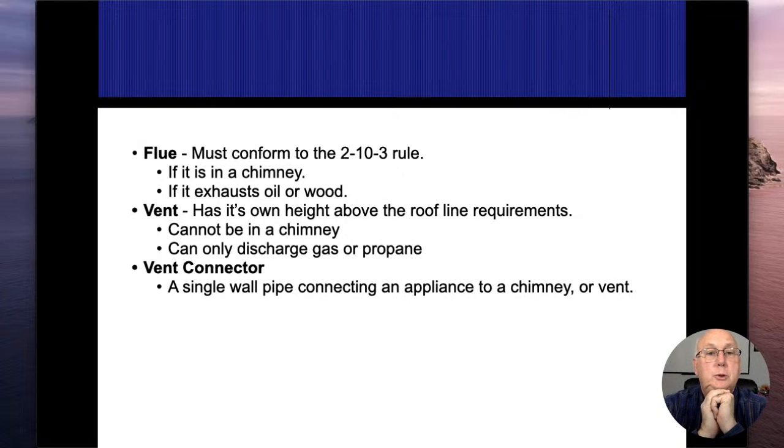All right. So venting, and this next section is going to talk about exhausting our bad gases after the fire. A little more terminology. I'd like you to know the difference between a flue, a vent, and a vent connector. All right. Flues, first of all, they have to conform to the 2-10-3 rule. That 2-10-3 rule is the height above a roof line that the top of a chimney or top of a flue needs to be.